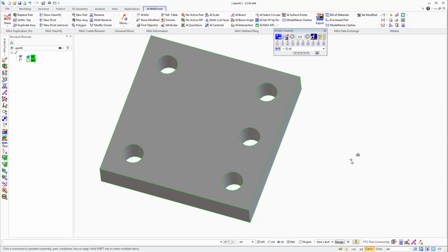In this example, I will demonstrate how to use the line between 2 points functionality in the 2D Copilot that was introduced in modeling version 19 and is available in all versions 19 and later. In the documentation, they show how to move a face, such as this face, into the middle of this part. The way that they do it is by putting a midpoint between these two holes, and a midpoint between these two holes, and then using the resultant midpoint of those two lines to place the center hole.